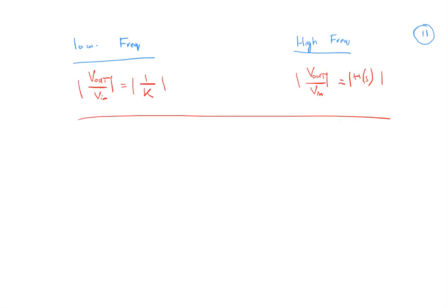Second thing, the general observation which we figured out is that omega unity is approximately equal to 1 over K times omega bandwidth. Now what is omega bandwidth? This is the closed loop bandwidth that we will have. Closed loop bandwidth. And K is equal to the feedback gain.